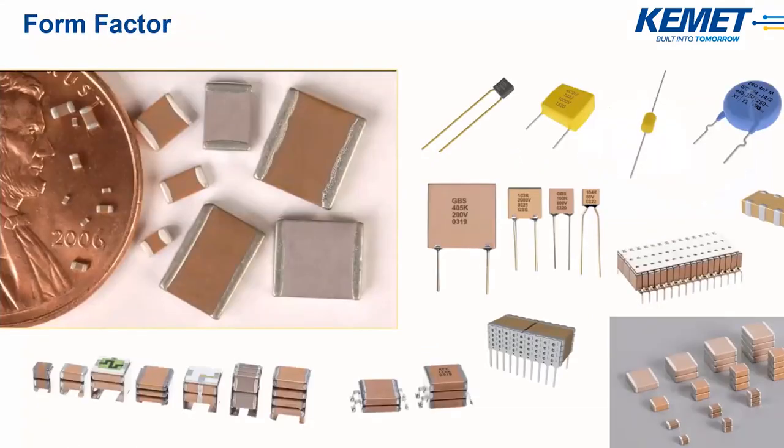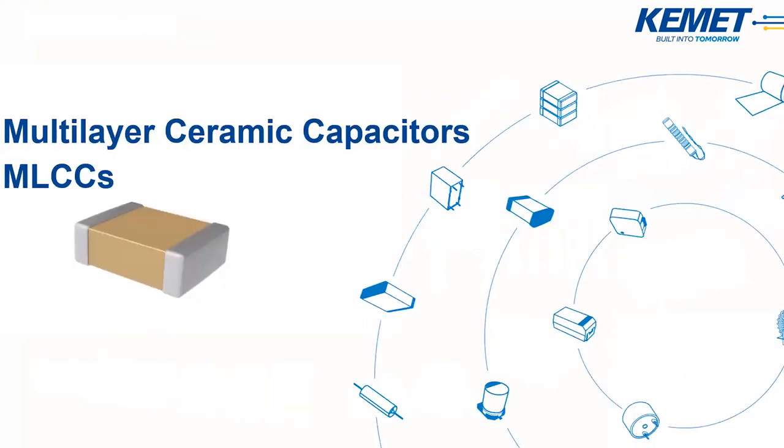So ceramic capacitors come in a variety of dielectrics, form factors, and sizes. These are driven by key application characteristics such as capacitance, voltage, temperature, and mechanical and reliability requirements. For example, applications with extreme vibration requirements may need ceramic capacitors with some type of mechanical absorption, such as lead frames. And here at KEMET, we offer many different form factors, such as surface mount, axial and radial leaded, lead frames, arrays, and many others. But for this presentation, we're really focused on multi-layer ceramic capacitors, or MLCCs.